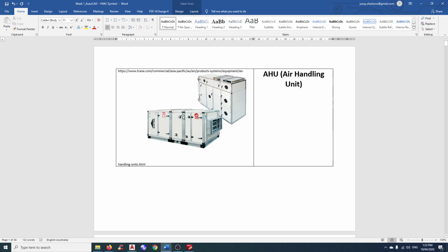And then this is the cooling coil, or in the system it will be just a refrigeration evaporator coil. Then you will have a fan chamber here. It comes in many combinations. It can be horizontal like that, it can be vertical, it can be horizontal and stacked. So there is no limit to how the air handling unit looks.